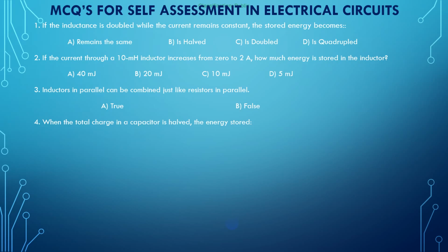Rearrange the equation. So half C is there. Now the voltage we can rearrange in terms of charge. The charge is equal to C times V, since the charge stored in the capacitance is nothing but C times V. Substitute it in half CV square, replacing voltage with charge.